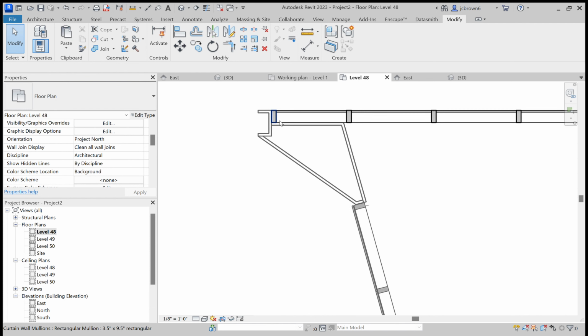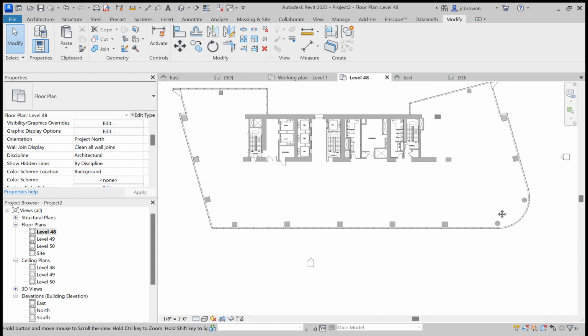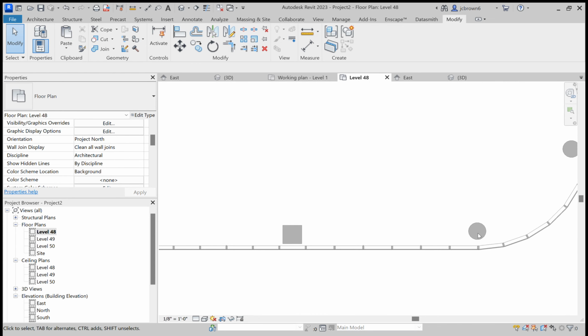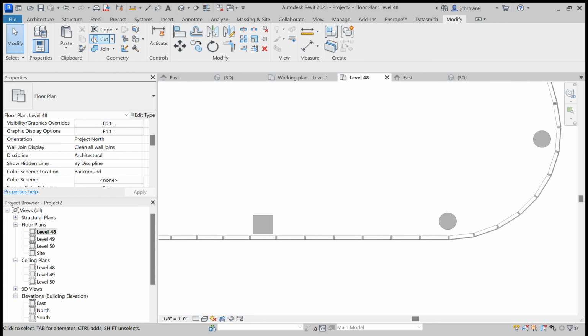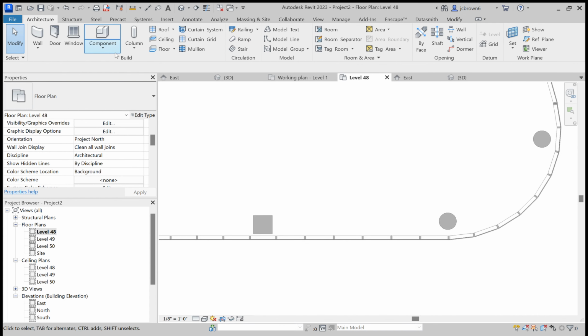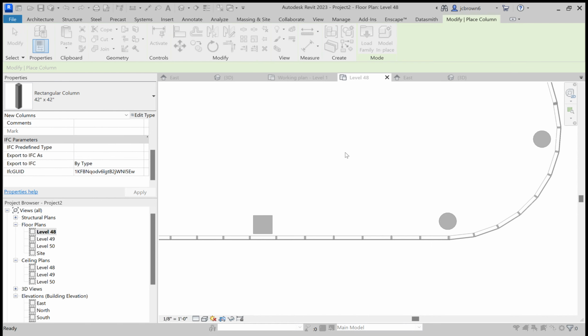These little guys that are on the side, I believe are like metal structures. So we will include those in our walls. And oh, let me go back to columns for a second. So the same way that you did the irregular columns, you'll also do the circle columns because you'll need to model those in place as well. So when you model those, you'll do the exact same thing. You'll go into architecture, column, here, and they're not rectilinear, so you'll need to model those in place.